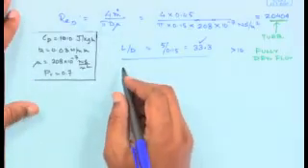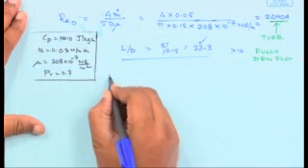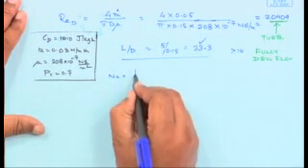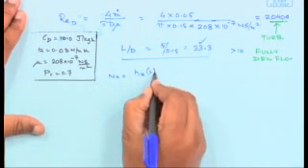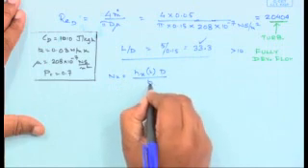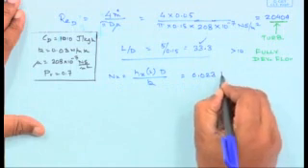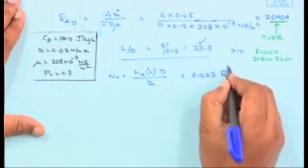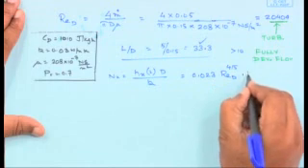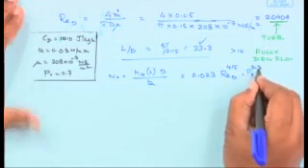So let's quickly evaluate the value of h, and then from there we find out the value of the total heat flux at that specific location. We are going to use the relation Nusselt number Nu_x at location L, which is h times d by k, the thermal conductivity, equals 0.023 Reynolds based on diameter to the power 4 by 5 into Prandtl to the power 0.3.